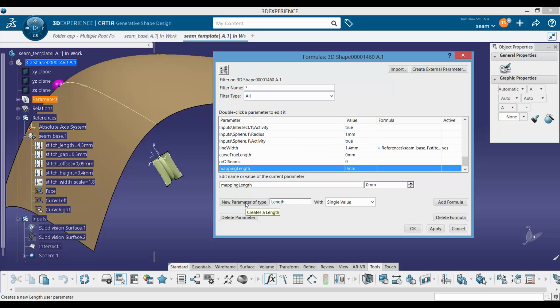And we can do one more parameter, again as an integer. So we will call this parameter extra elements, extra seams, which will give us the possibility to add an extra element, to squeeze it a bit more if necessary. This is quite useful when the integer is not really rounded how we want it, because the integer will be rounded up by 0.5 millimeter, and sometimes a 0.5 millimeter bigger element looks less appealing than two smaller elements that are sharing this 0.5 millimeter.